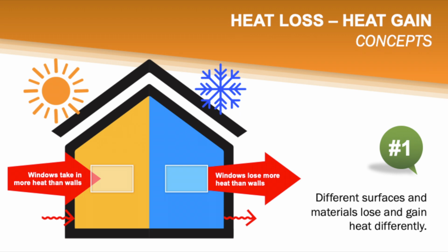Ceilings just below a roof or attic space require more insulation than walls to control heat loss and heat gain. Even if there is no attic, a flat roof directly exposed to sunlight can gain a great deal of heat. To reduce the amount of heat lost in winter and gained in the summer, insulation is very important. The more insulation, the less heat gain or heat loss you will have.